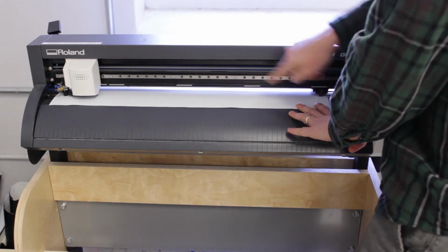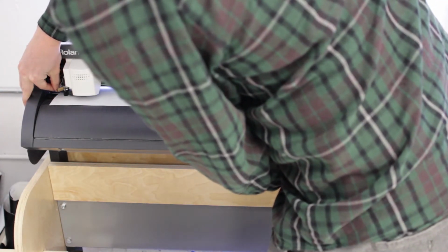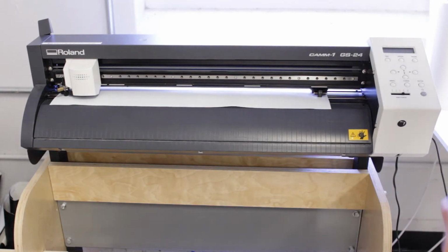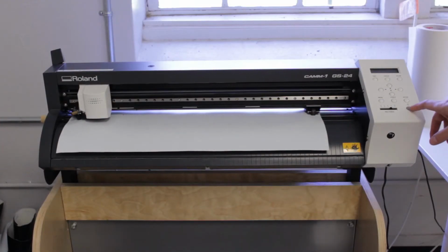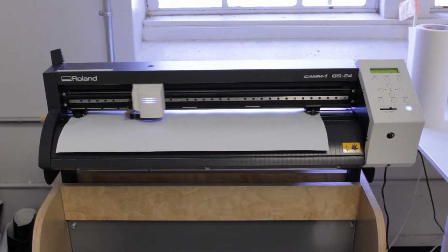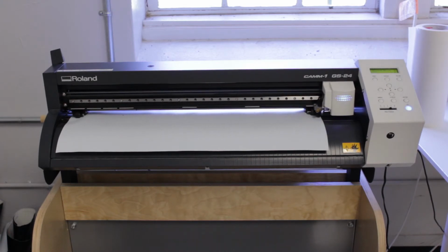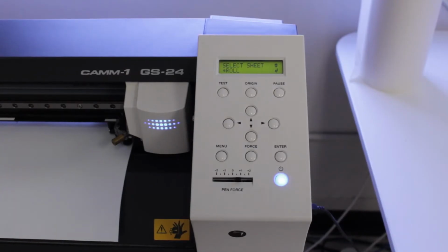These wheels must be placed inside the white dashes on the axis of the machine. You may lift the clamp lever to the up position, clamping the wheels down onto your material. When you are finished setting up the material, press the power button. The cutting head will travel to the right-hand side of the machine.